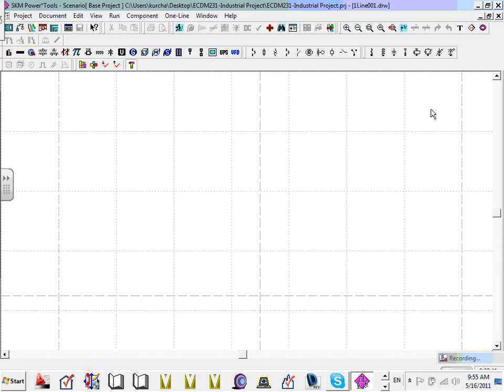Okay, grab your one-line diagram and you can follow directly with me, guys. Here's how we build it. We build the one-line diagram, or the riser, directly in this. We start from the utility. Look at this row here. These are your components. Remember, it's modeling. Don't drop anything yet, I'm just going to quickly show you. Where you hit New Bus, a bus is like a panel. Think of it as a panel.